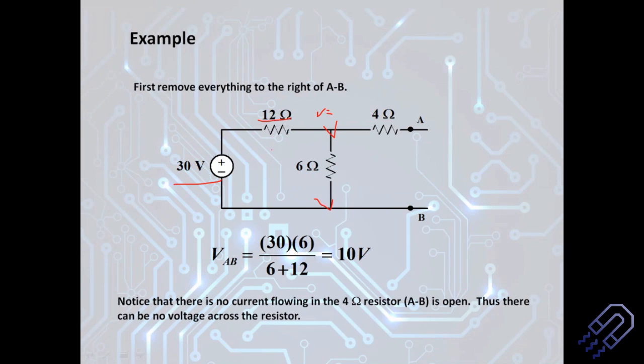So that will be nothing but 30 divided by 18, right? Something like that. So if you do the calculation, from V is equal to IR you find out what is I, and then you can just take I into R. So that means current into resistance, subtracted from 30, will be the potential drop here. Okay, that is the value.